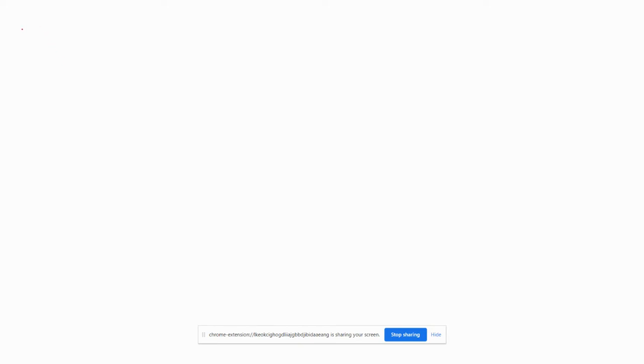So now we have to find the weight percentage and mole percentage. So first let us write the component, and we have found the quantity in weight, that is kgs. So first is picric acid, and the second is phenol. Okay, picric acid is product, phenol is unreacted reactant, and the next is water, product.